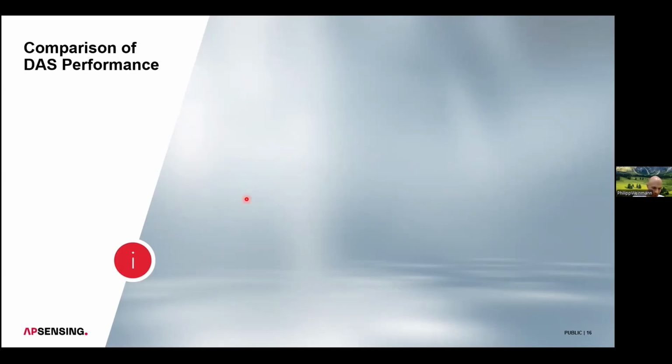Whenever a train is passing by, the train generates an acoustic wave which travels into the ground and gets reflected by the different layers. The glass fiber, which is now used by the DAS system, captures the back reflections. From these back reflections, you can study whether there are sinkholes below the train track. I think that somehow relates to the question, no?